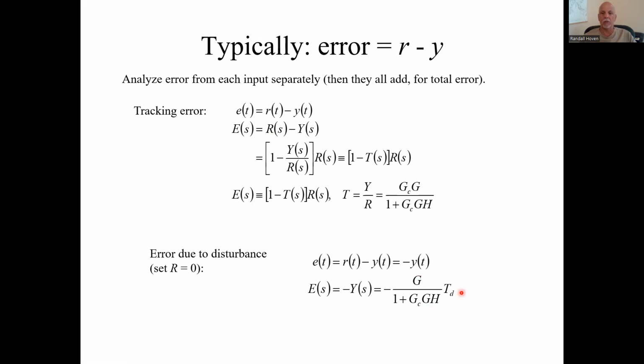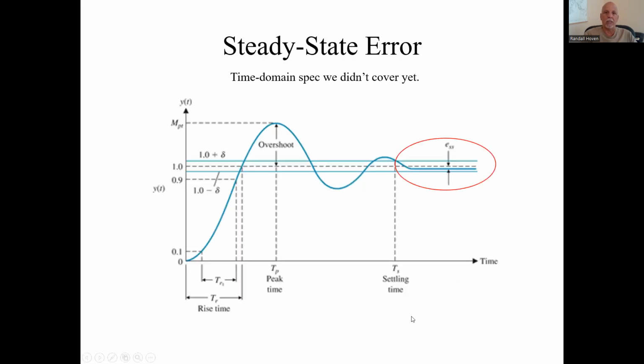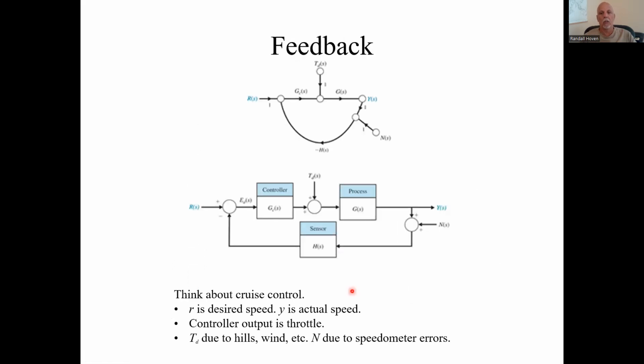So here's that transfer function, and let me go back to the block diagram that it comes from. I'm looking at, remember the error was minus y? I'm looking at it with respect to this T sub d, this disturbance input. In that case, this process here is the forward path gain, and the product of these two guys is the feedback path.